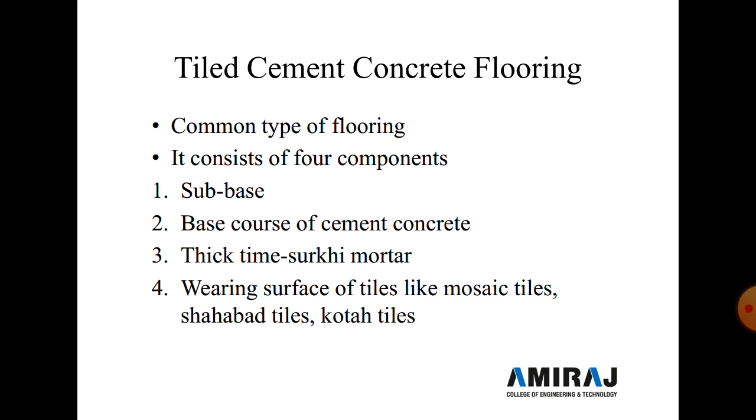So the base course of 50 to 80 mm thick lime mortar with a ratio of 1:3, meaning 1 part of lime and 3 parts of sand or surkhi, is spread to fix the tiles, and the bedding mortar is allowed to be hardened for 12 to 24 hours.